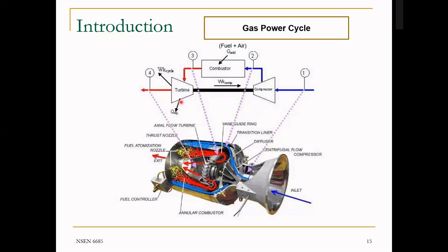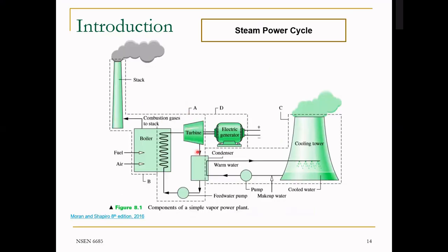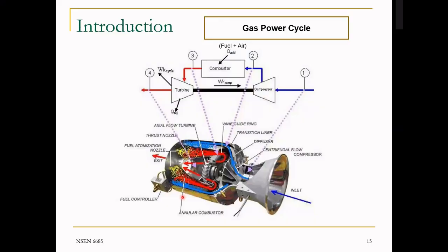But sadly, the exhaust coming out of the turbine is really super hot. So we have to cool it down, very typical to what we did in the steam cycle. Whatever is coming out of the turbine, we have to cool it down to condense it so it can go through the pump. We do the same here. We take the exhaust of the turbine and cool it down with a recuperator, or what we call a heat exchanger. Then we put it back to the compressor and the cycle continues.